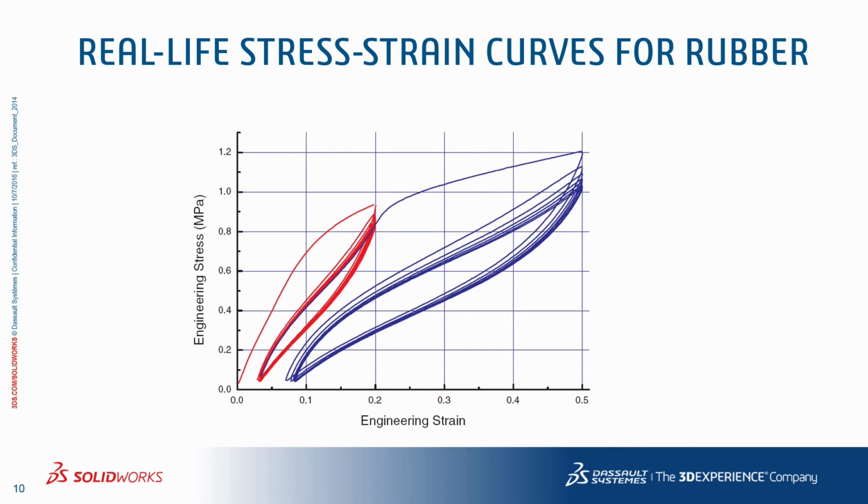Now, with hyperelastic materials, once a material is manufactured, it undergoes cyclic loading and unloading for at least about 25 to 50 times to stabilize its response, as shown here. Now, during the initial loading and unloading of these raw materials, notice how the stress strain response differs or is offset from its previous cycle of loading and unloading. After repetitive loading and unloading, the material starts to follow a constant loading and unloading path, and the stress strain data corresponding to this stable configuration is what is needed in the analysis input.